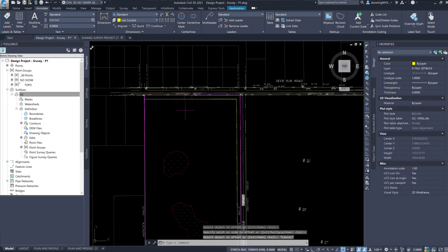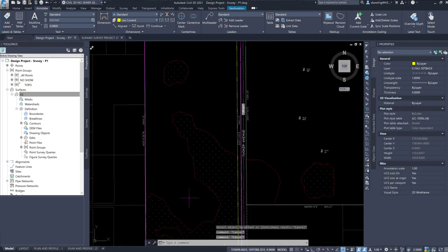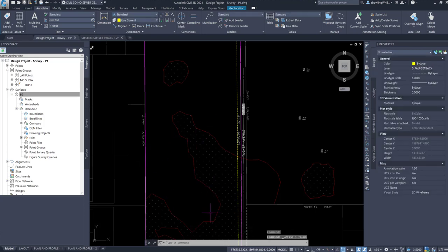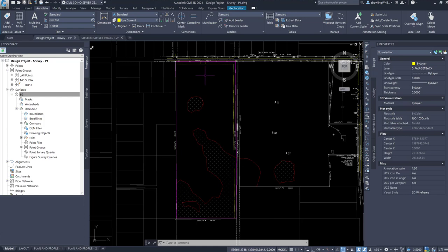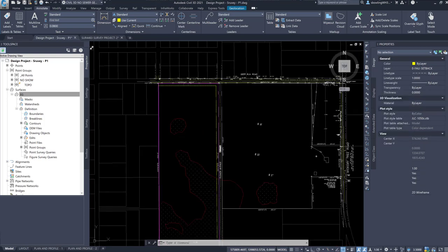I could bring a road in through here and then meander this direction and then meander this direction and down in here to build houses. Now the distance between here and here, I just drew a line, is going to be 252 feet. Okay. Now, this might be one of those where a park is set or your pond is set. Okay. Ponds need to go at the lowest point of your site, and this is one of the lower points of your site. So what I would recommend doing is kind of figuring out where your pond needs to go.